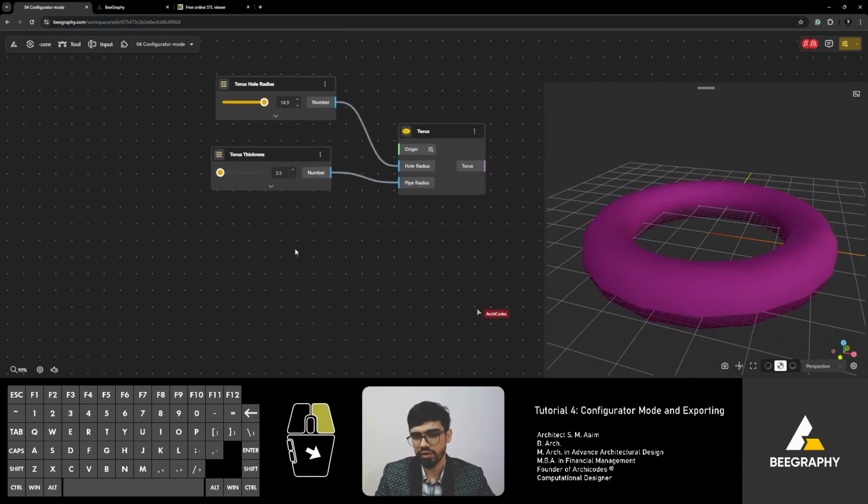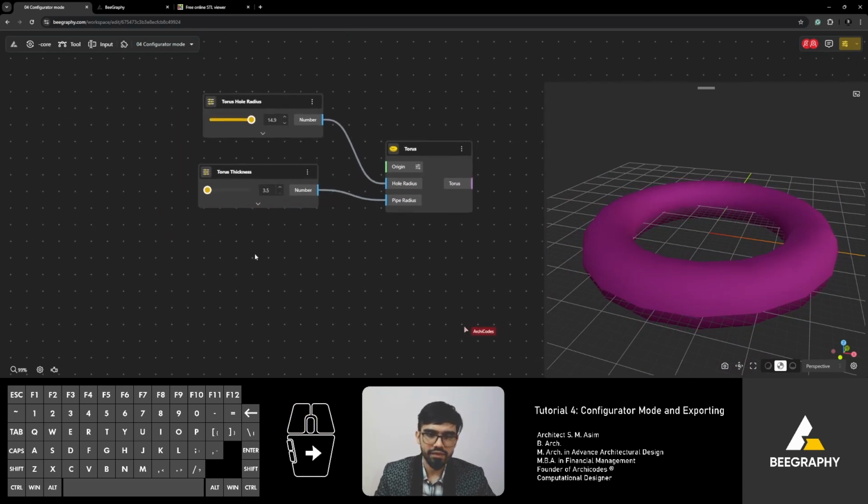Now a few shortcuts. Let's say you want a range input from 5 to 15 without doing all of this hassle. So just type in 5 less than 15 and then press enter and you'll get a range input in integers from 5 to 15. The less than sign is simply shift and then press comma. So it's above that.